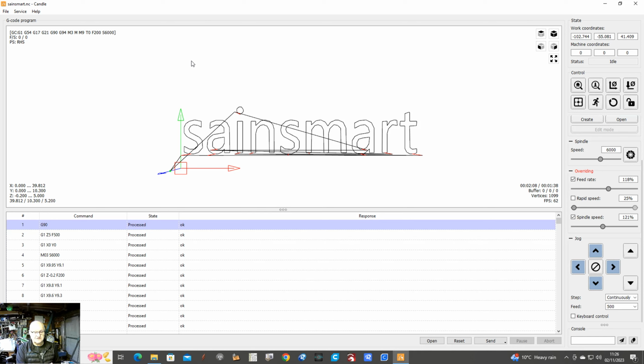Or what I do sometimes is I'll have a piece of the same material I am using on the bed of the machine, and then I'll change the cutter, bring it over, and touch off on that. Once I've done that, you've zeroed off, because it's the same thickness material as the job.